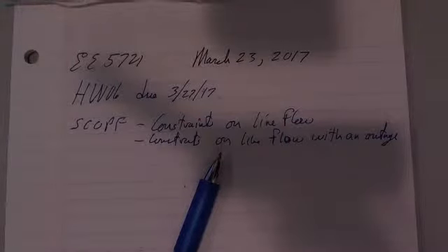But if you have some difficulties, maybe there's some lines out for maintenance. Anyway, as soon as you put a line flow limit, the cost is going to go up. And as soon as you constrain it to not have any overloads with a contingency, the costs go up even more. So much of the time, those kinds of constraints are active during peak loads.